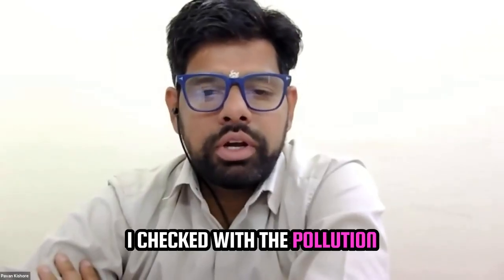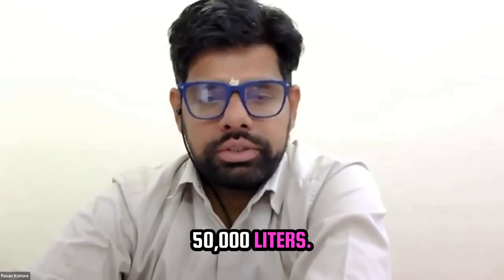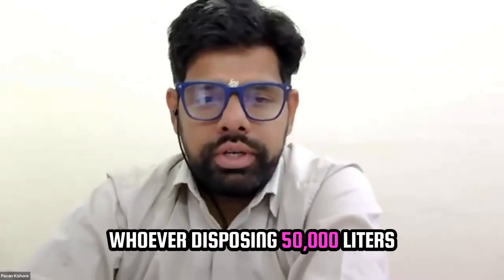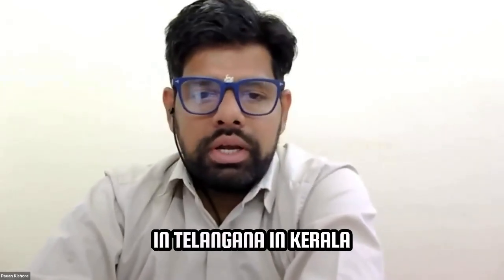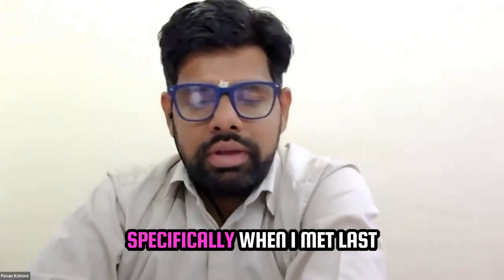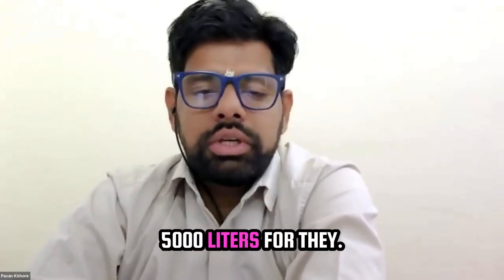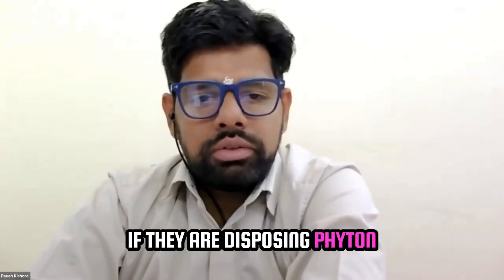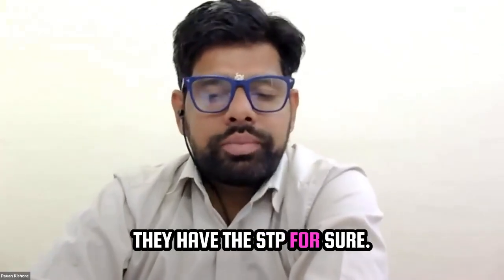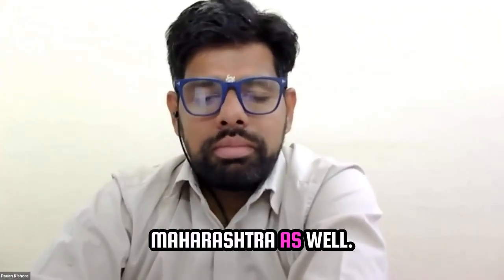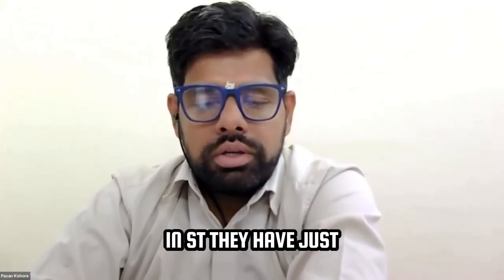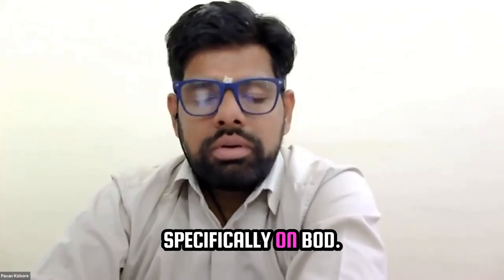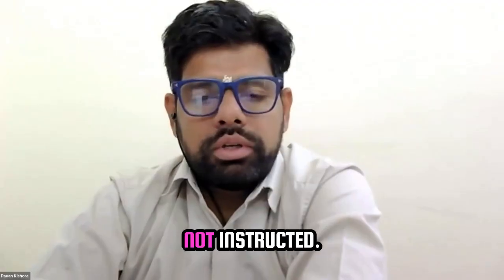And sir, here I want to add, sir. I've checked with the Pollution Control Board, sir. In Hyderabad, whoever is disposing above 50,000 liters has to have an STP. In Kerala specifically, when I met them last time, they said 5,000 liters. If they are disposing 5,000, they have to have an STP for sure. It is the same with Maharashtra as well, but Maharashtra is not so stringent. They have specified only BOD. That's all. They have not instructed more.